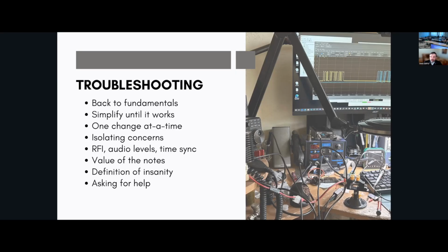Anytime you have the circumstance where everything works okay until the first time you transmit, the RFI would be the first suspect. When things break irrationally, illogically, RFI is the suspect because it will make things glitch. And once things are glitching, anything can happen.